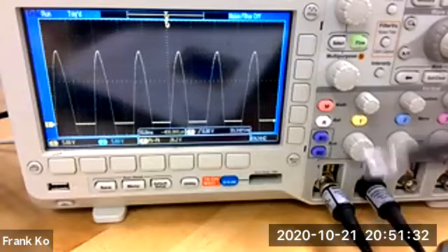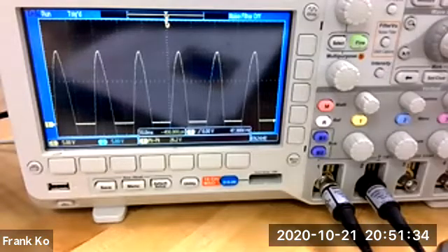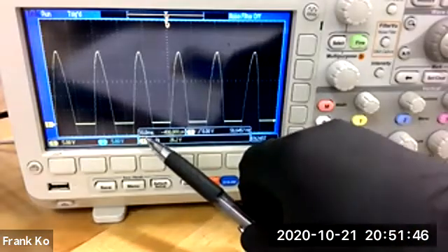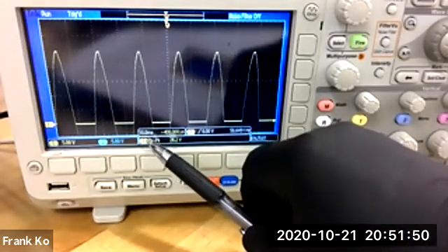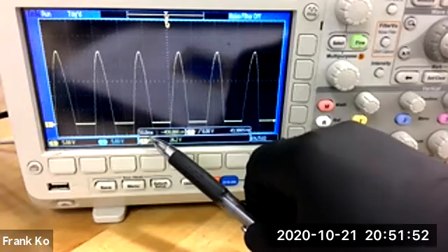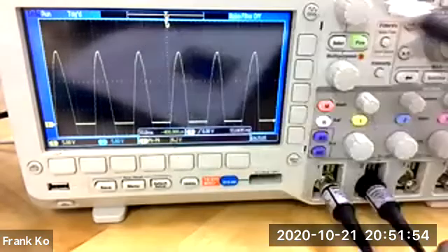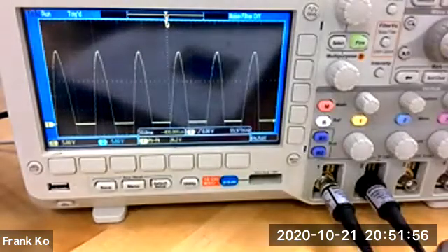The best way for you to see this also with your horizontal scale is to make sure your horizontal scale is set, in this particular case, what do I have this set to? 10 milliseconds per division, okay? So could you set your oscopes to be 10 milliseconds per division, and we achieve something that looks like this. I will come around and check your displays.